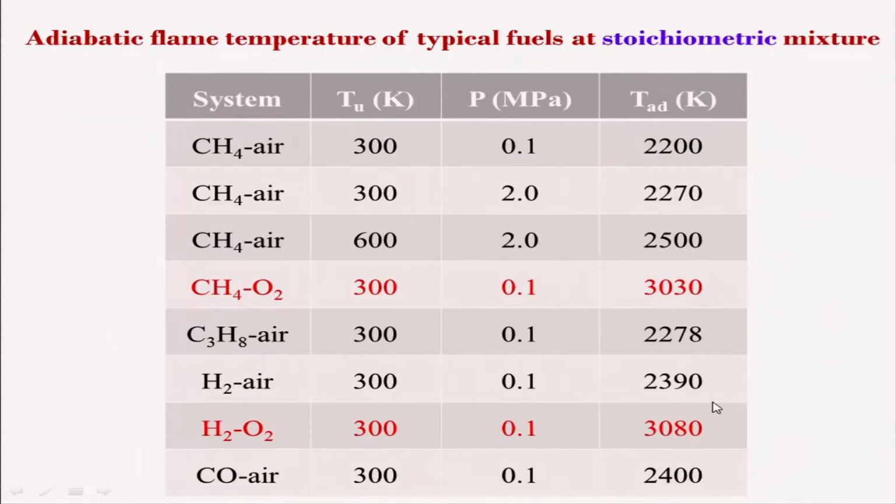So, therefore, the adiabatic temperature will depend not only on the fuel air ratio, it will depend on the inlet temperature, and also on whether it is air or oxygen or any other thing. So, basically we will stop here. We have learned how to apply the first law of thermodynamics to reacting systems, and we have also seen how to calculate adiabatic temperature, and it will also be dependent on the pressure.